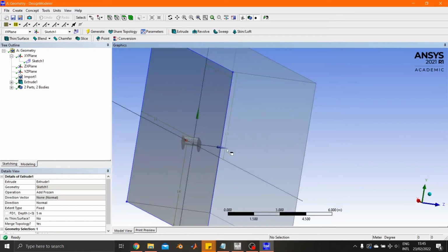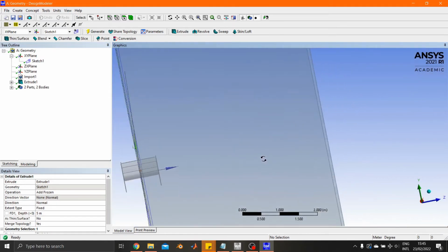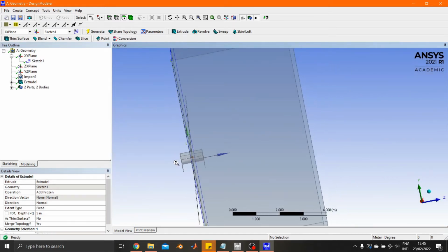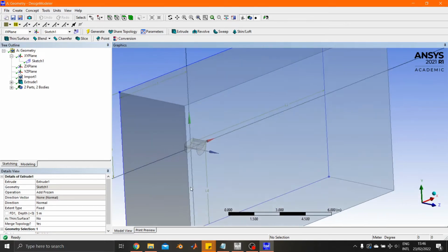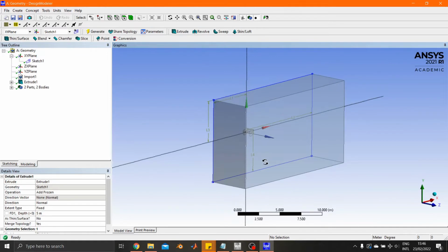And as we can see, half of our part has been left out right here. It's not part of the box, and that's because we only want to simulate half of it, and then we can multiply whatever force values we get from the simulation by 2 to simulate what the full wing would be. But because it's symmetrical, it just saves computing hours if you only do half of it. So that's one part of it.